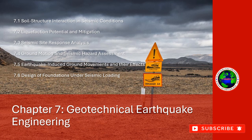Soil structure interaction, SSI, refers to the mutual influence between the foundation and the surrounding soil during an earthquake. This interaction can amplify or dampen seismic forces depending on factors such as the type of soil, foundation stiffness, and the dynamic properties of the structure.